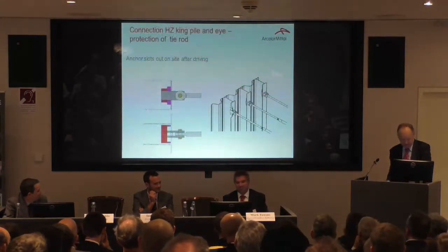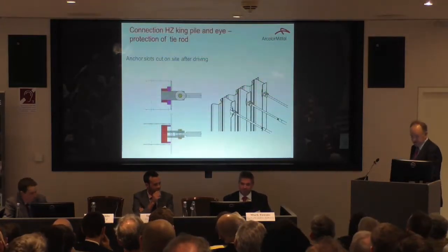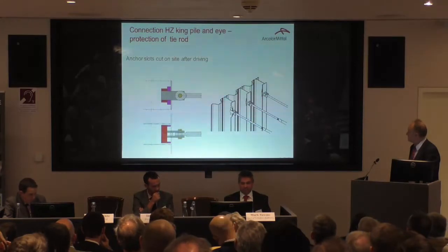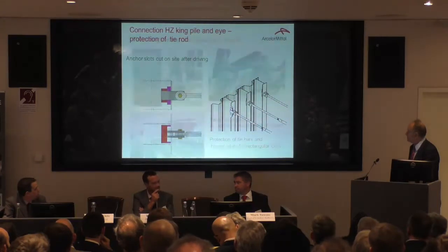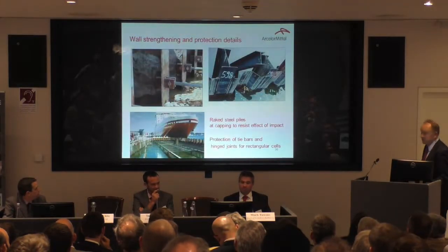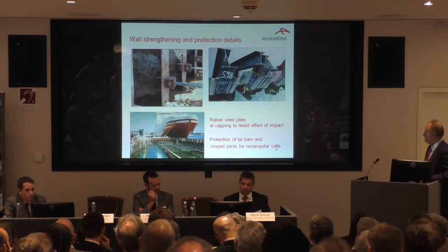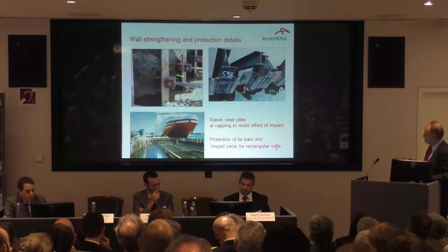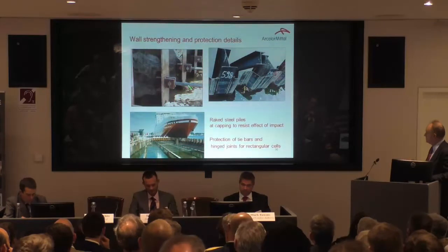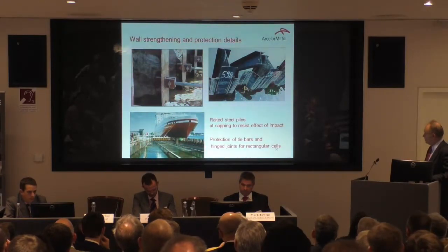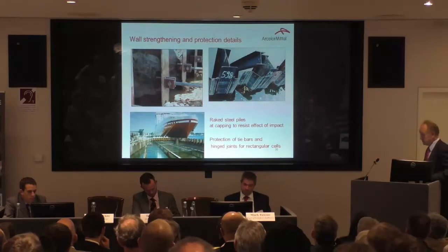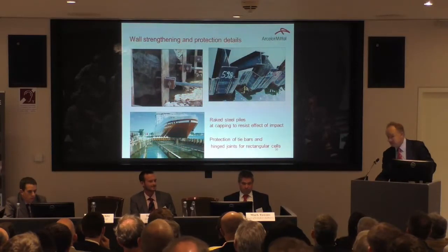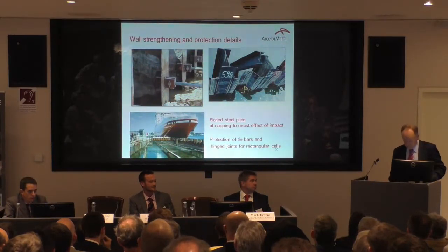So, thank you very much. I just had an illustration here of tiebacks to the 8Zs, where the tiebacks are protected by connecting onto the back flange, and you increase robustness by protecting the top and being able to dewater and connect on the inside rear flange of the 8Z. In this way, the whole process of construction inside the cofferdam can be maintained in as robust a fashion as possible.